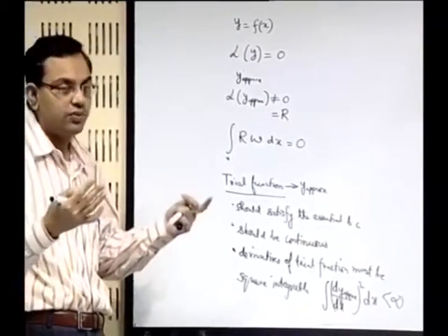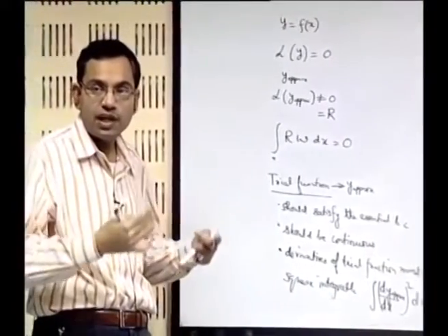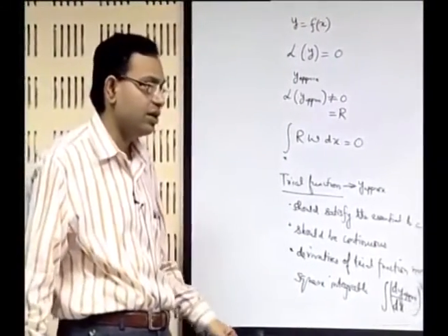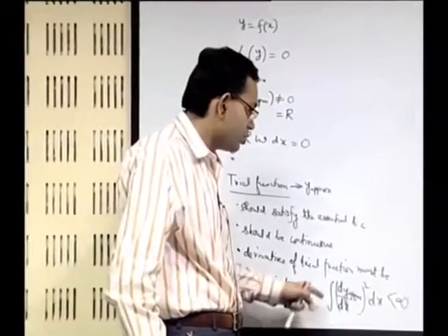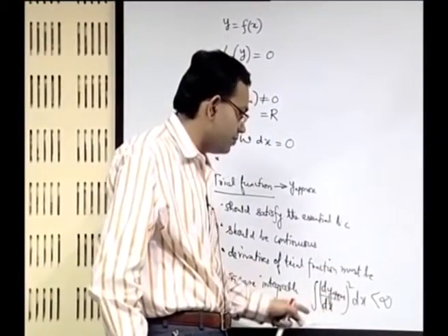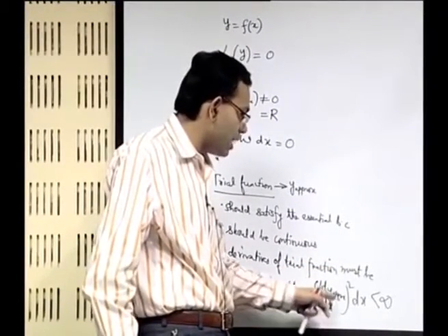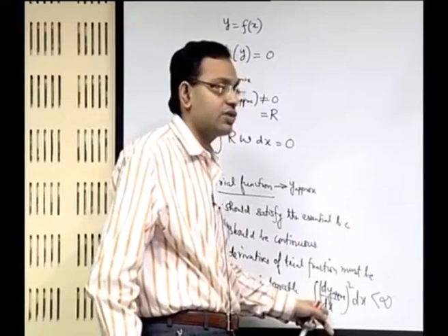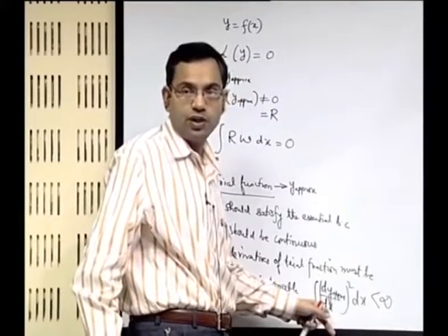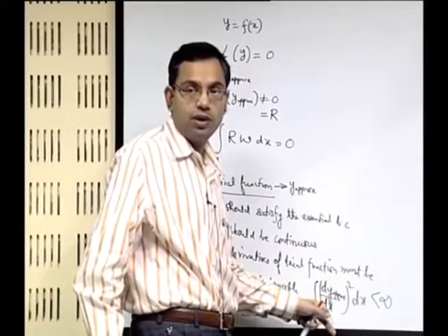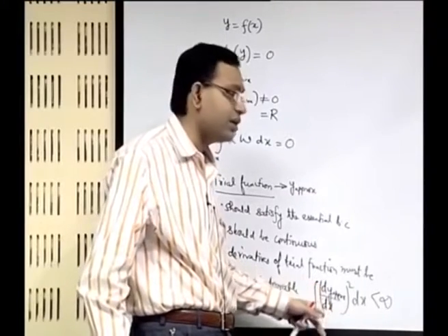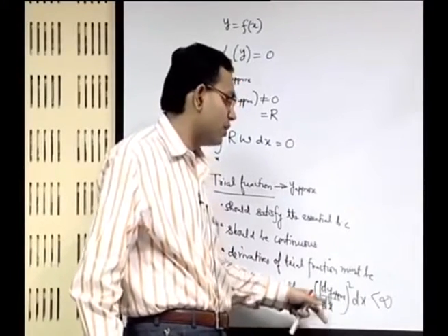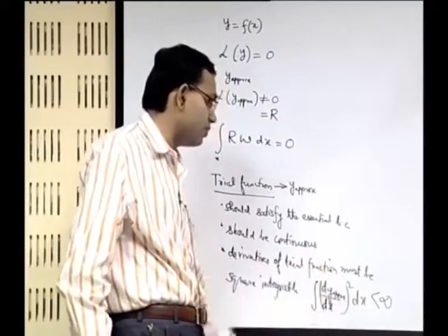Similarly, for a fourth order problem, it would be a second order highest order derivative continuity requirement. So, if it is a second order problem, then you only require up to the dy dx type of term for your continuity requirement. You do not require any higher order derivative corresponding to your variational formulation.